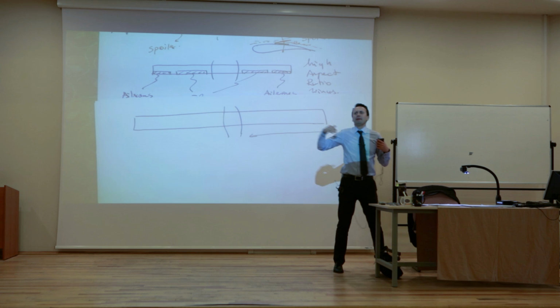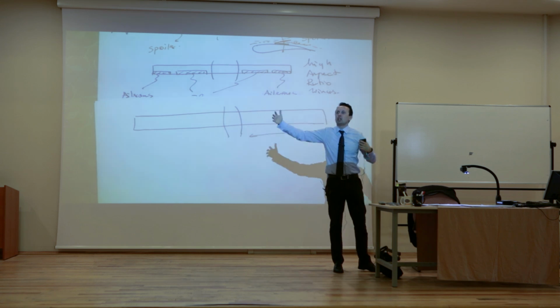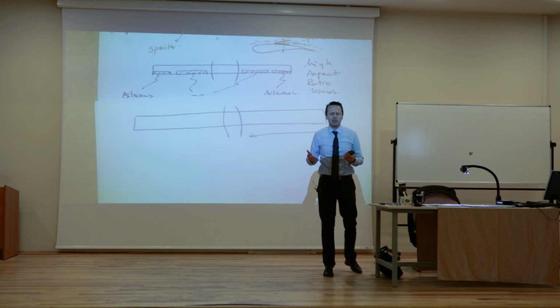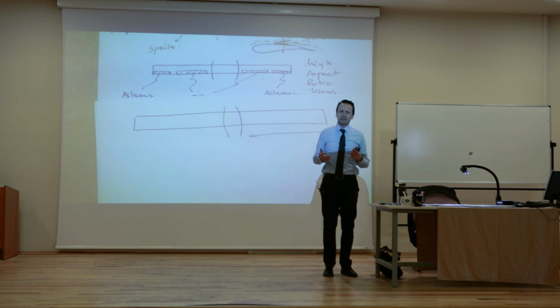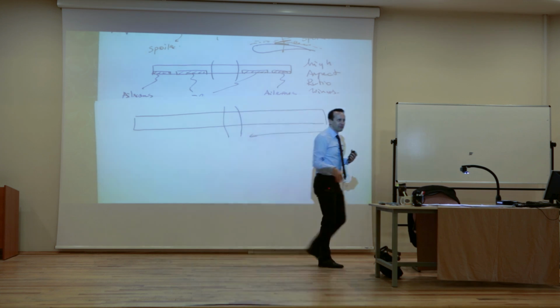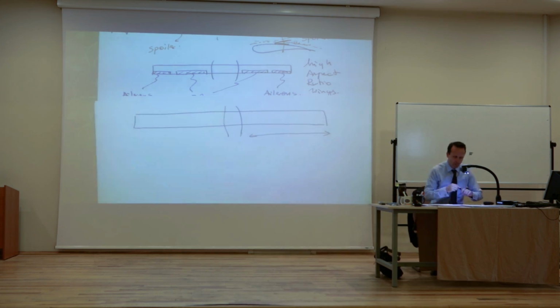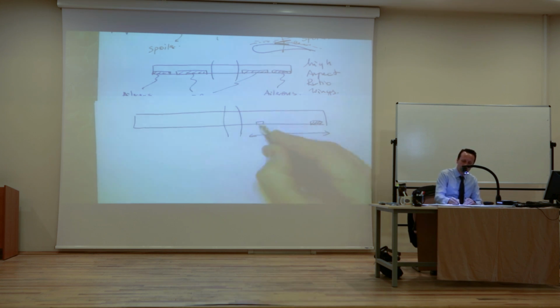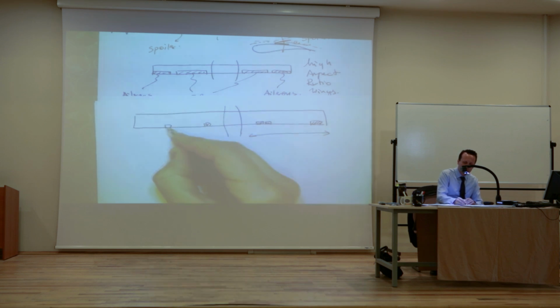Now, if you have a really big wing, listen, if you have a really large wing, imagine the A380. You know the Airbus 380? It's a huge wing, huge airplane. I mean, that wing probably has a lot of aeroelastic modes. So you need to suppress those modes. And an aileron over here might not be enough to suppress those modes. So what do you do? You have that little thing here, but you might have a few control surfaces over here as well, or maybe somewhere over here.